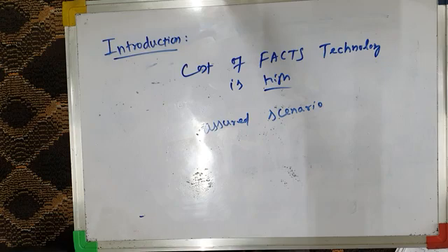The existing transmission networks can be made to handle more and more active power as the load demand increases. Then improved transient stability and damping of power oscillations. So these are some of the main advantages offered by FACTS technology in our highly interconnected power systems.